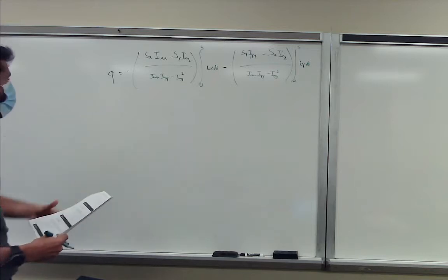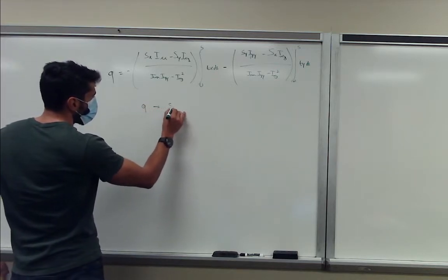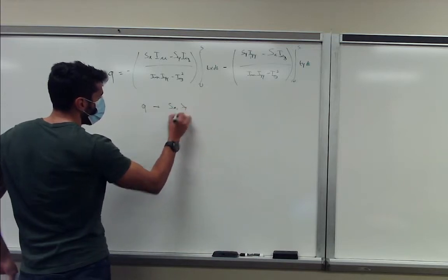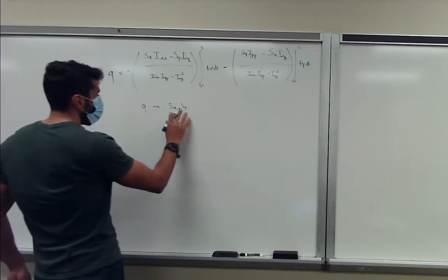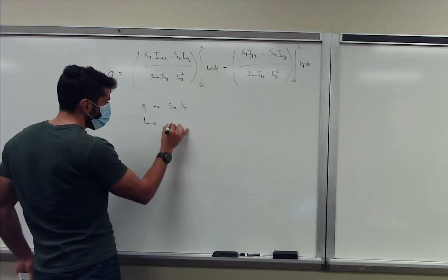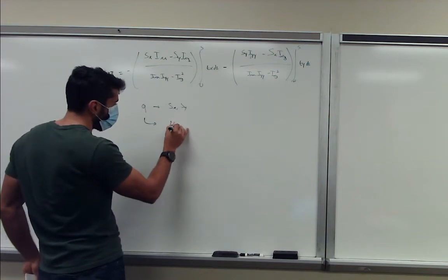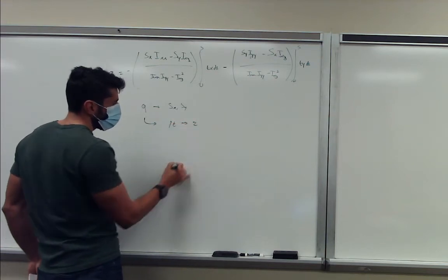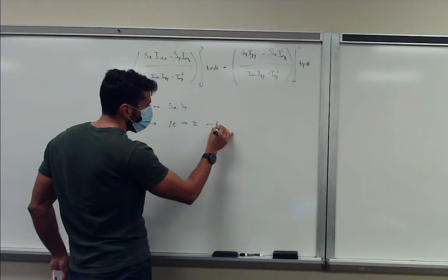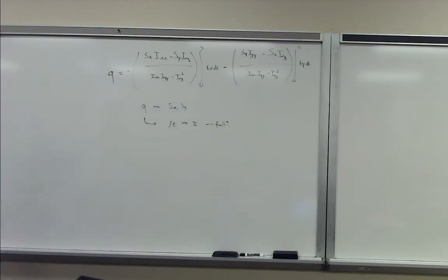So basically this relates our shear flows to our shear forces Sx and Sy. And once we have our shear flow, we can multiply by thickness to get force, if you have a force to design for, or we divide by thickness to get our shear stresses, and then we can see if it fails or not. So that's the steps that we think of.